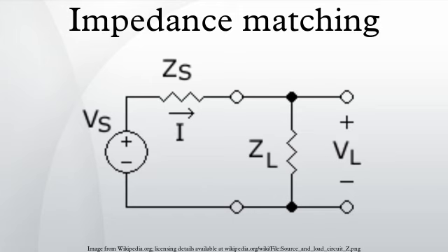In older audio systems, the source and load resistances were matched at 600 ohms. One reason for this was to maximize power transfer, as there were no amplifiers available that could restore lost signal. Another reason was to ensure correct operation of the hybrid transformers used at central exchange equipment to separate outgoing from incoming speech, so these could be amplified or fed to a 4-wire circuit. Most modern audio circuits, on the other hand, use active amplification and filtering and can use voltage bridging connections for greatest accuracy. Strictly speaking, impedance matching only applies when both source and load devices are linear.